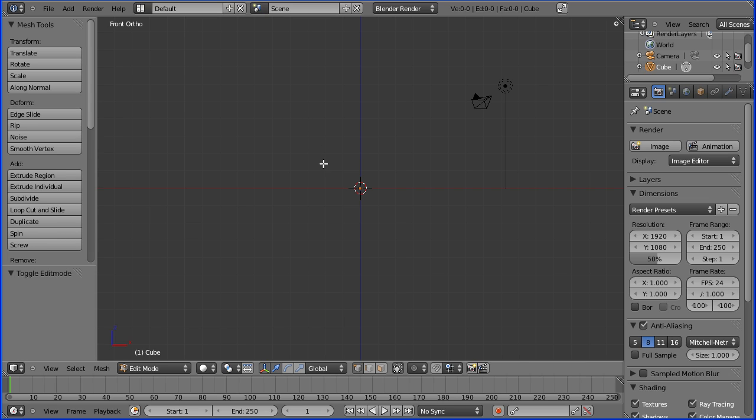I'm going to draw the cup, the bowl of the goblet, just above the red line x-axis, and the stem and the stand underneath. To make the goblet a closed shape, you need to have the first and last vertex on the Z-axis, on the blue line. I'm holding down Control and I'm clicking the left mouse button, and so I'll draw a bowl shape.